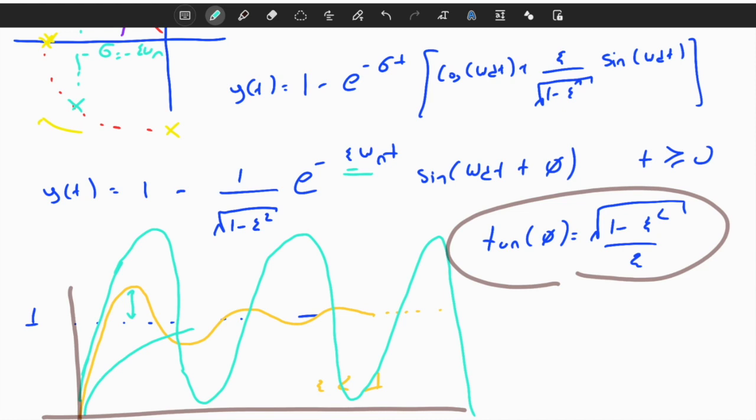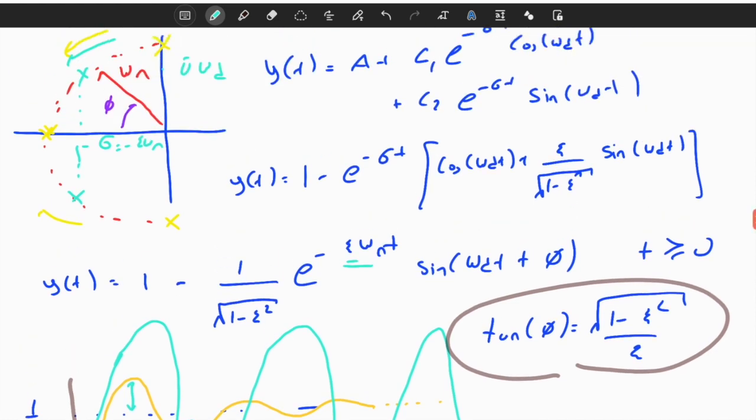So what's happening if I increase damping? I'm approaching the critical damped case. Similarly, in the overdamped case, if I decrease my damping, I approach the critical damped case. So the basic idea is that the best response in a second order system is the critical damped case. If you cannot achieve this exactly, you try to manage such that you are at least close to it. You can be a little bit overdamped or a little bit underdamped, and it will still be okay. You may have some oscillations, you may lose some speed, but it will still be close to the optimal response.